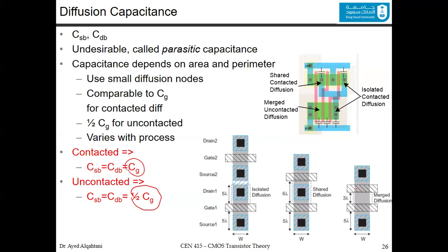First, if you have two poly gates, remember, for example, this circuit, we discussed this before, and we say that this is 3 transistors in series. If we say that this is A, and this is B, and this is C, so we have A ANDed with B, ANDed with C. I'm looking at the pull-down network here. And we will say A B C bar, and this is our output or our function. If we say that this node here is the function F.